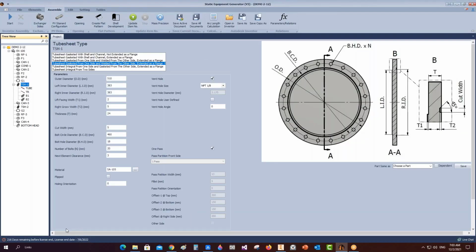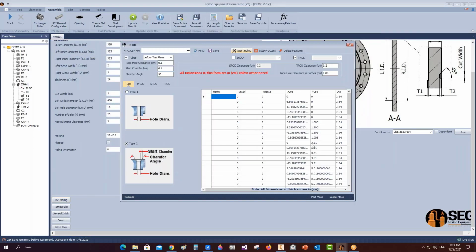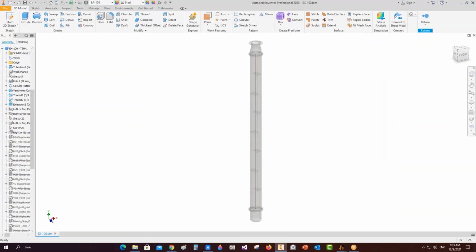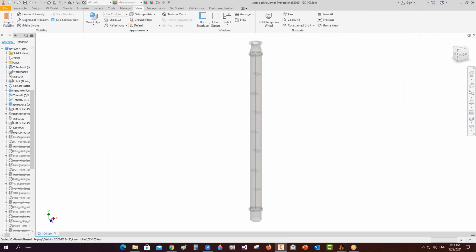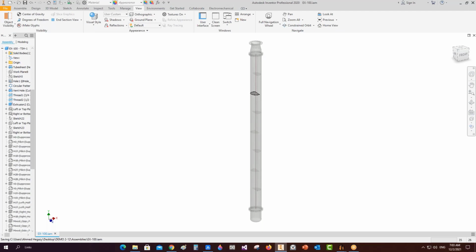And from here, let's select the tube sheet tooling. And let's start the tube sheet tooling. Those dimensions come from our calculation, the location, tools. We will need to click on start tooling, and SEG will start creating tube sheet tooling and tube and tie rod pattern. This process may take between 1 or 2 minutes to complete. It's based on the number of rows required on the model.